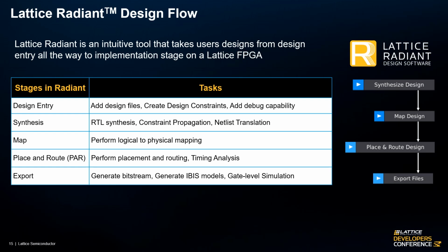Design entry is where the design for the FPGA is being created or entered. This includes design files using hardware descriptive language, such as VHDL or Verilog. This is also where timing and physical constraints are included. Debug capability could also be added if needed.